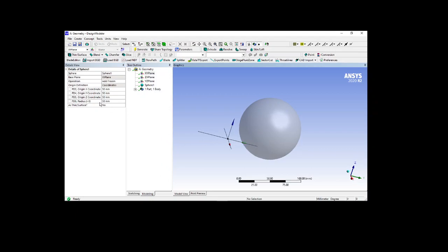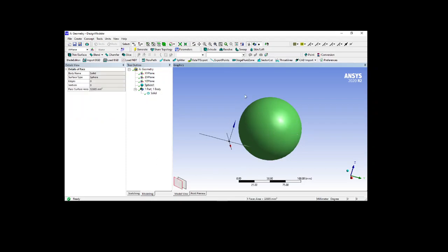Another option is thin surface, as I have already told you. If you want a thin surface, then press yes, then give the measurement of thin surface, how much you want. Here the 1 mm is enough for me. That is, I want to take the 1 mm outside instead of inside. Then if I create this, it will give our body, which is a solid body of surface. Okay, so now the inside of this sphere is eliminated, and the outer surface is formed. Okay, this is how.